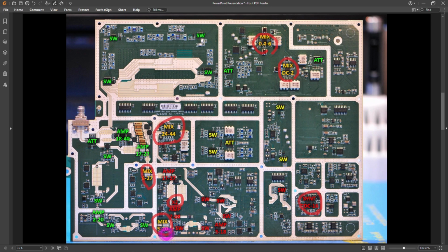And then we have mixers that cover up to 20 and up to 27. And all these mixers are always coupled with a gallium arsenide amplifier, either on the LO path or of course on the RF path. And that also helps us see the frequency planning. So for example, an amp over here in the RF path covering 2 to 20 gigahertz tells us that that signal has to reach a mixer roughly in the same frequency range, because these are direct conversion systems. And the switches that you see here are parts of the filter bank sitting in the RF port. Similarly, if you have a mixer up here that works from 24 to 44 gigahertz, we're going to have an amp that gets you essentially close to those frequencies, and it's exactly what is happening over here.